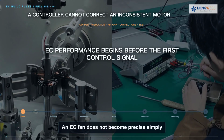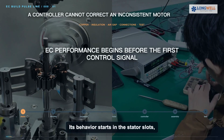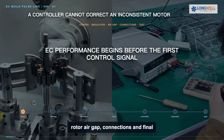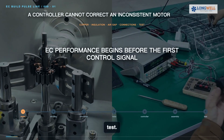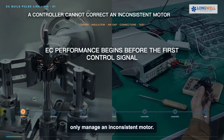An EC fan does not become precise simply because a controller is attached. Its behavior starts in the stator slots, copper path, insulation, rotor air gap, connections, and final test. Miss one link, and the controller may only manage an inconsistent motor.